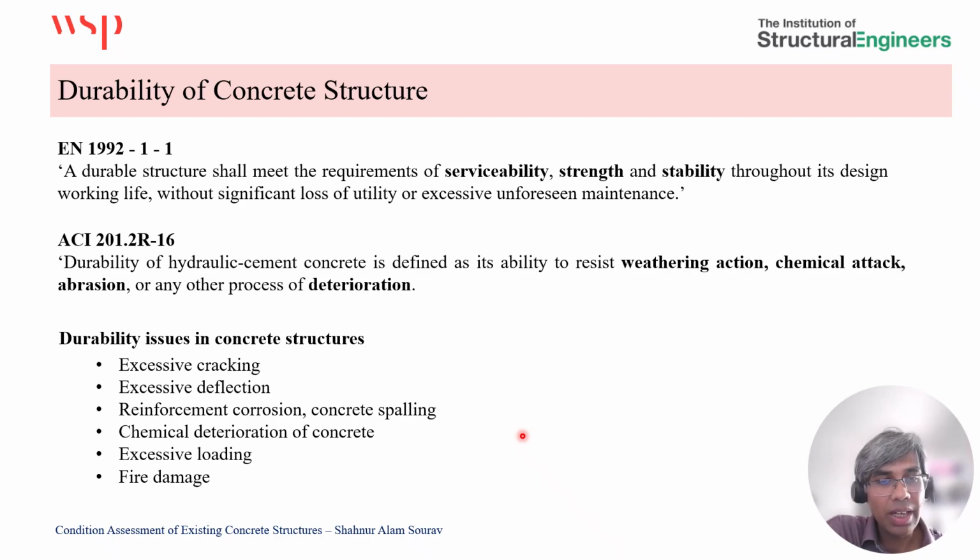According to ACI 201.2, which has a similar definition, durability is defined as the ability to resist weathering condition, chemical attack, abrasion, or any other process of deterioration. So durability issues in concrete structures can occur for various reasons. It can be due to excessive cracking or deflection, which can be the result of excessive loading. It can occur due to reinforcement corrosion and spalling, chemical deterioration of concrete material itself. It can occur due to fire damage as well.